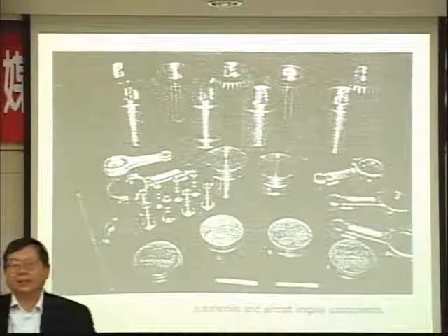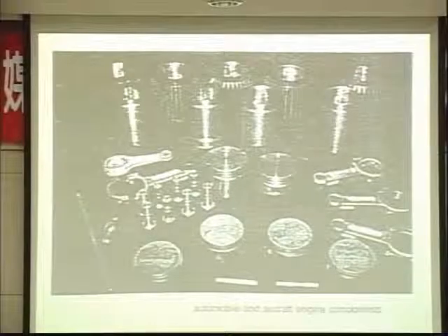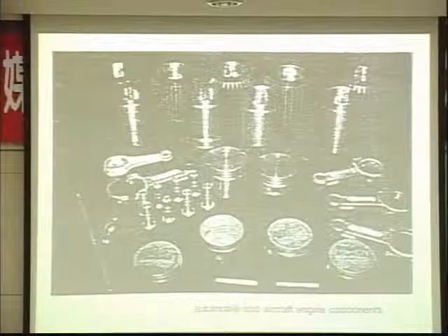We developed a process using a very special technique, an infrared technique, to make composite material. So Toyota wanted to use a composite for their brake rotor. We had a joint program with Toyota and tried to make it. I was making composite about that size, 1 inch, but they wanted 1 foot, 10 to 12 inch. So I had to restructure my infrared furnace to make it huge.